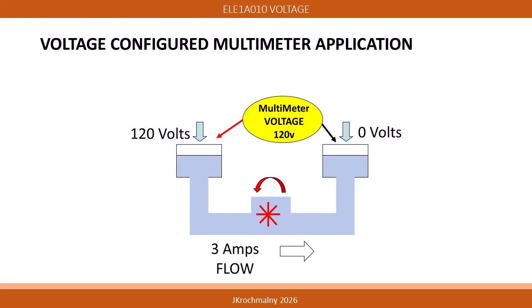An electrical test instrument called a multimeter can be placed between 2 points of a circuit to measure voltage pressure differences. In this case, 120 volts on one side and 0 volts on the other results in a meter measurement of 120 volts of pressure difference. The electrical term for electrical flow is identified as the ampere or the amp. Amperes, like GPM in water circuits, is one value referencing two conditions, quantity and units of time, which is indicative of a flow of a material.